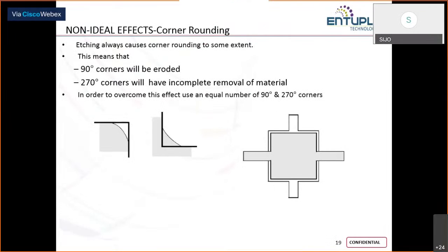As I told when we discussed the resistor layout, we generally try to avoid 90-degree corners, because the current will not be uniform there, and it's also very tough to measure the resistance at the end when we do the EM analysis and measure. So what is the problem if you go with a 90-degree corner or 270-degree corner? That is what you can see on the left corner of your design.